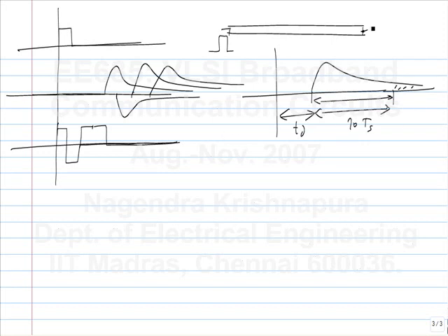So by taking the bits out, you don't really take anything out; you simply look at the value of the voltage. It's not like you are resetting the transmission line, shorting it out and reducing all the fields inside the transmission line to 0 at that point. You send bits one after another. This bit will have an effect; you will start seeing it only after TD, because of the finite speed of the wave. And it has some effect after 10 TS also. That depends on the actual characteristics.